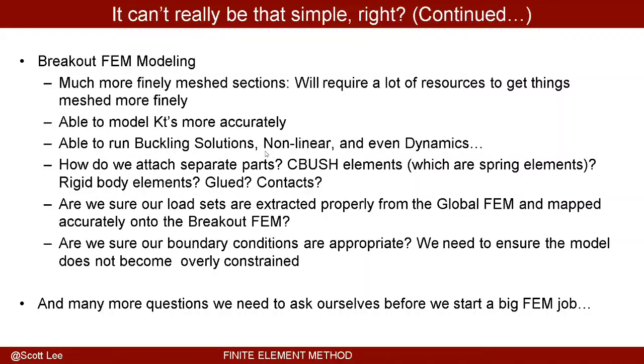So our loads that we apply to the airframe include the factor of safety. Typically from the aerodynamics group, we're going to get a distribution of load across the aircraft. And in finite elements, everything's discretized, right? So essentially what they provide us are either pressurized loads or basically grid point forces, so loading at each of the nodes with a certain magnitude. And they typically apply those with a 1.5 scale factor. And that 1.5 scale factor is basically our factor of safety.